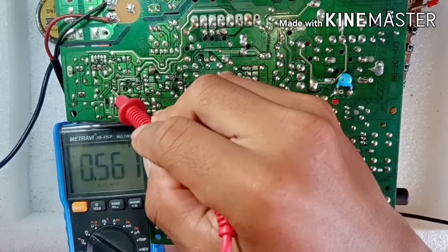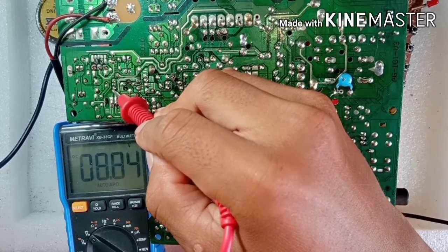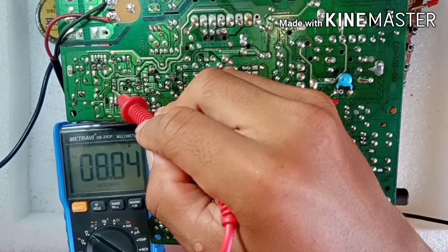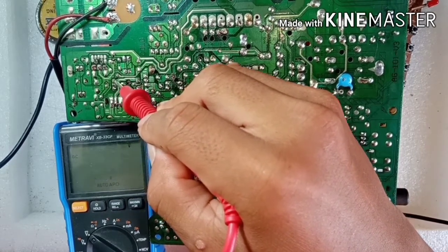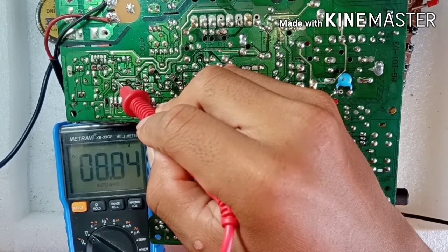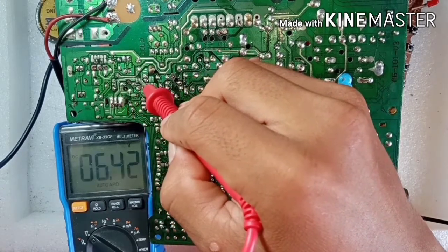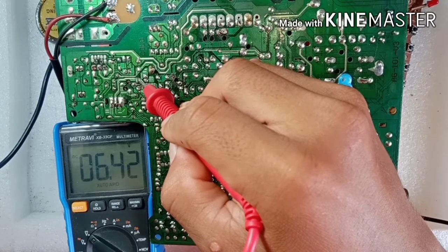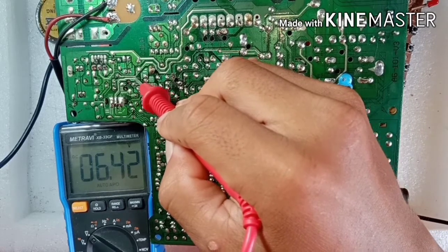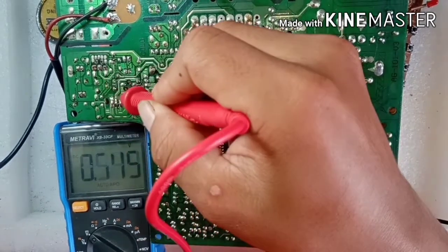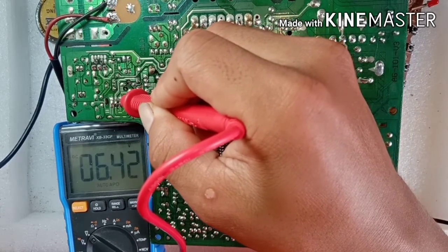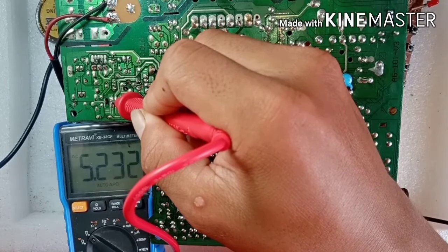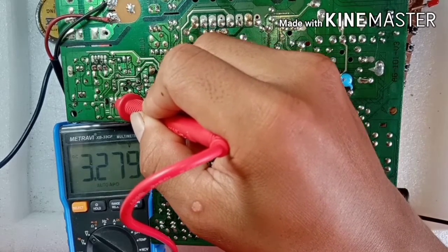It will continue going through that trace and reach the input of the resistor that I have replaced. Now we get 8 volts out from the first resistor instead of the 1.3 volts before, and this 8 volts is going to the second resistor and we have 6.4 out, and this 6.4 volts is directly going into the input pin of the regulator, and it will be regulated down to a constant and regulated 5 volts. Now 5 volts is available.